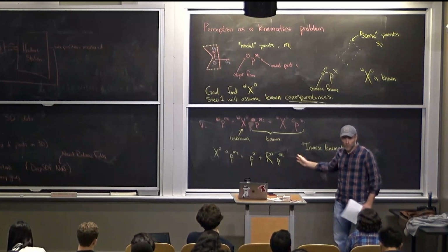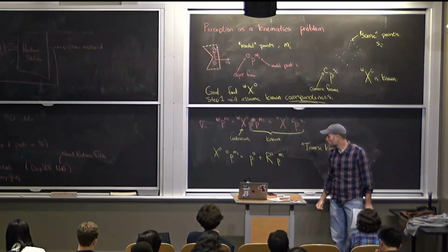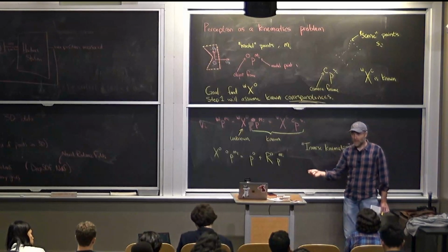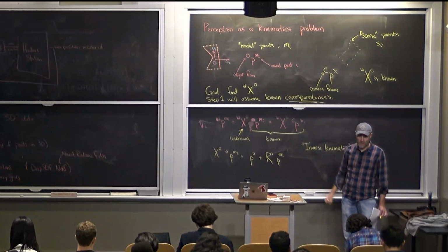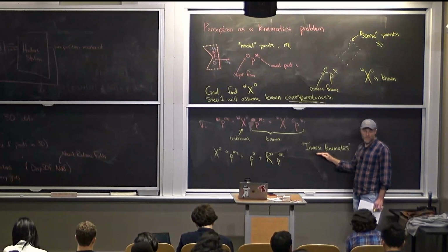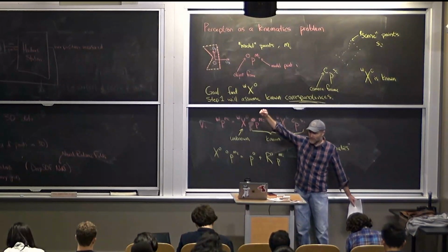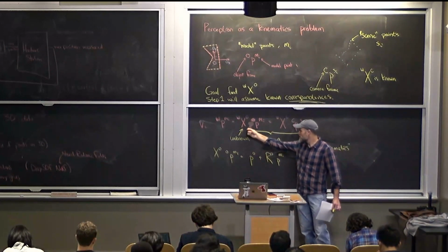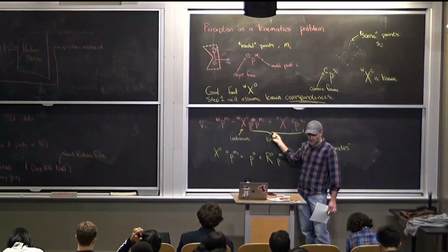But we're saying at least once you have to figure out the hard problem, find the needle in the haystack potentially. Now, once you solve that once, I actually would advocate differential inverse kinematics if you wanted to track, for instance. If you want to do real-time tracking, then by all means you should be thinking about gradients and the like. But the one-time problem must be solved in the perception case. Fortunately, this is not some complicated chain of equations that can lead to lots of nonlinearities and local minima. This is about the simplest inverse kinematics problem we could have to solve, and we're going to see it has beautiful structure and good solutions.